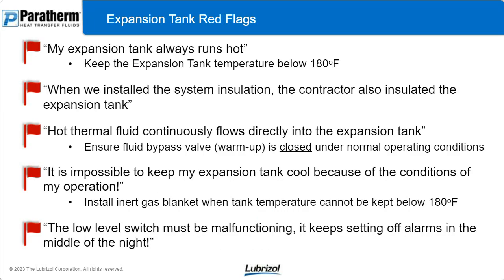So, red flags within the expansion tank. If you're telling me that your expansion tank always runs hot, that's a big red flag. If you don't have a hot expansion tank, you won't have oxidation. We're trying to avoid oxidation. So always keep your expansion tank somewhere below 180 degrees Fahrenheit at max. You want to make sure that it's as low as possible, but 180 is usually where oxidation starts to really accelerate. If you put the investment in to have some good insulation on your system, and whoever put the insulation on actually insulated the expansion tank, big red flag, take the insulation off the tank.